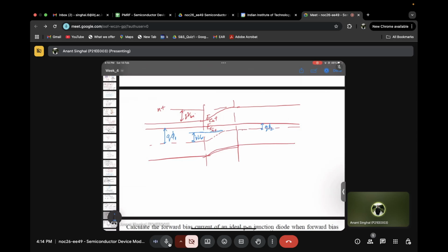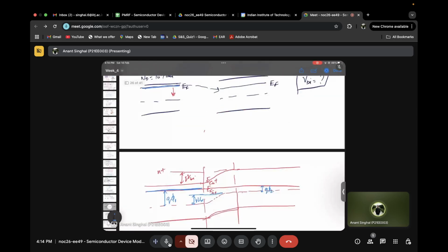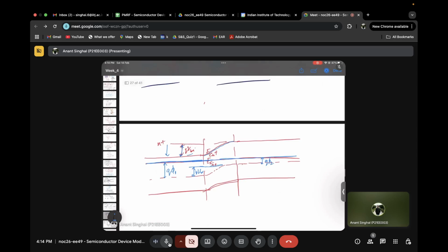So what I am saying is, this is the Fermi level which is close to the n-type, which is here. The electron will flow from the energy level which is higher, the Fermi level which is higher than that of this. So this needs to go down. I've just pushed this down. So this is the Fermi level that is aligned now, and this is the band bending. This band bending is actually the built-in potential, right? This was the same in the p-n junction case. But the band bending here, my point is, this is Ei, this is Ei, right? Ei minus EF was q phi n for the n case, and let's say I'm writing q phi 1 and this is q phi 2. This is Ei minus EF only. Is this clear?